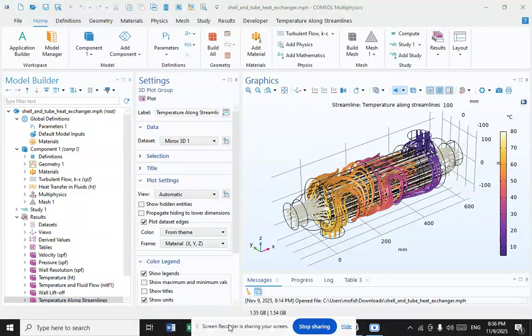And the next one is tubes and fin design. In applications to cool air with shell and tube technologies, such as an intercooler or charged air cooler for a combustion engine, the difference in heat transfer between air and cold fluid can be such that there is a need to increase heat transfer area on the air side. For this function, fins can be added on the tubes to increase heat transfer area on the air side and create tubes and fins configurations.